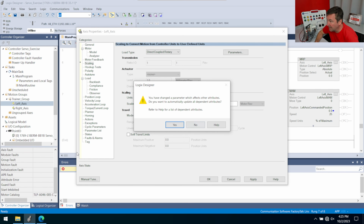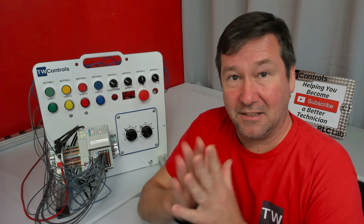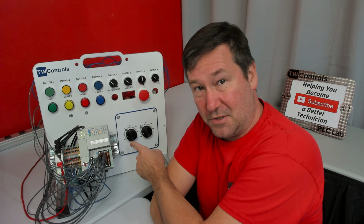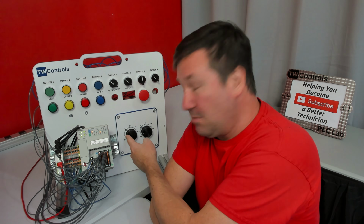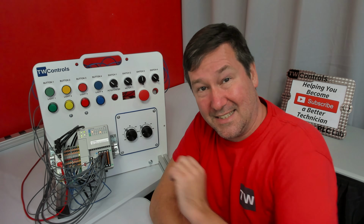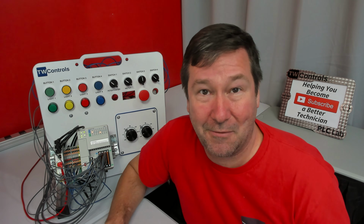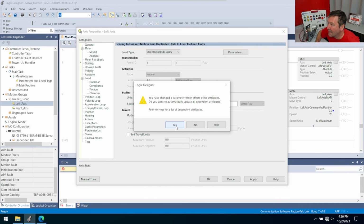We can click help and get the dependent attributes, but let's mainly talk about it. Right now our speed is in revolutions per second. And so we set our maximum speed to 2 revolutions a second. And that's going to be incredibly slow when we make this 360. So let's see what happens. We're going to go ahead and click yes to this.